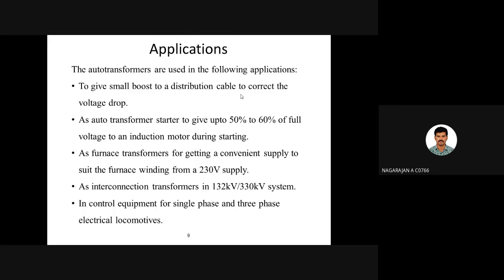So when resistance is connected in a higher value, a huge amount of voltage will be dropped in the resistor itself, and only the remaining part will go to the fan coil. For example, you are applying 230 volts. Out of 230 volts, I'll be wasting 200 volts in the resistors itself. Only 30 volts will be going to the fan. So the fan will be running at slow speed.